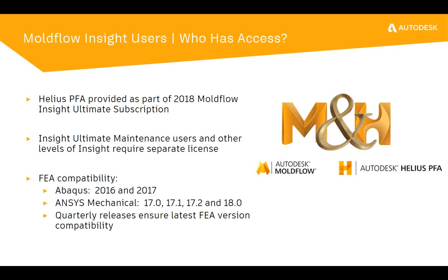So what that means is the coupons that we're using to generate our data, our material properties, have residual stresses. All right, so here comes the tricky part, right? We know there's residual stresses, but the test data that we're using to evaluate how harsh those residual stresses are is compared to test data where those residual stresses aren't accounted for, right? They're zeroed out. We look at that stress strain curve, that first data point's at 0, right?